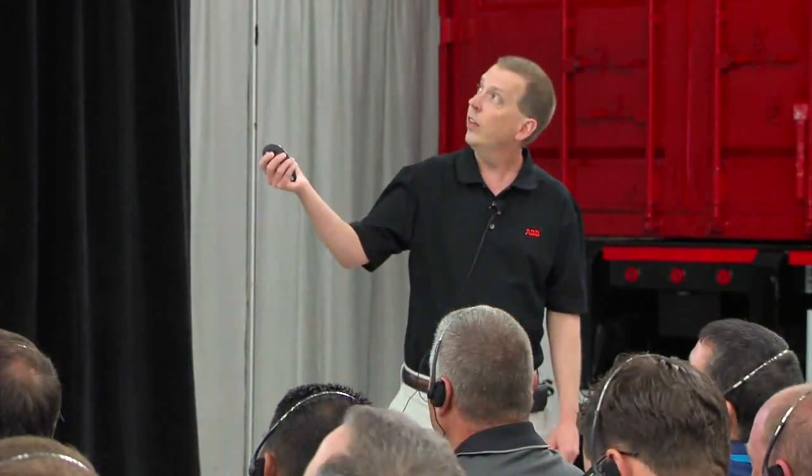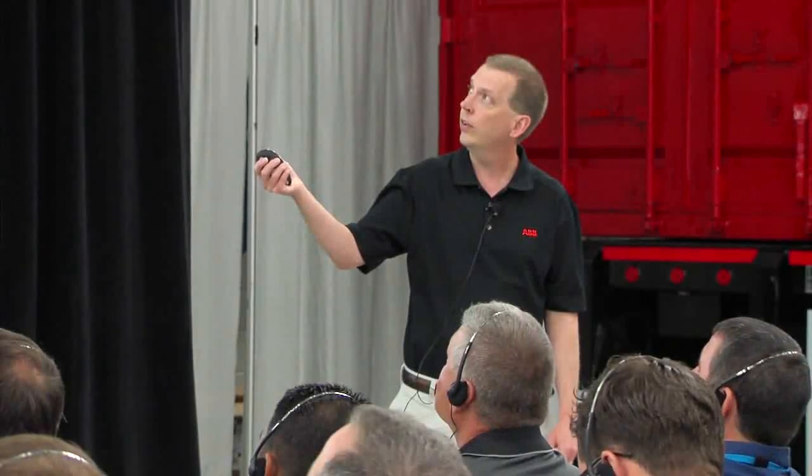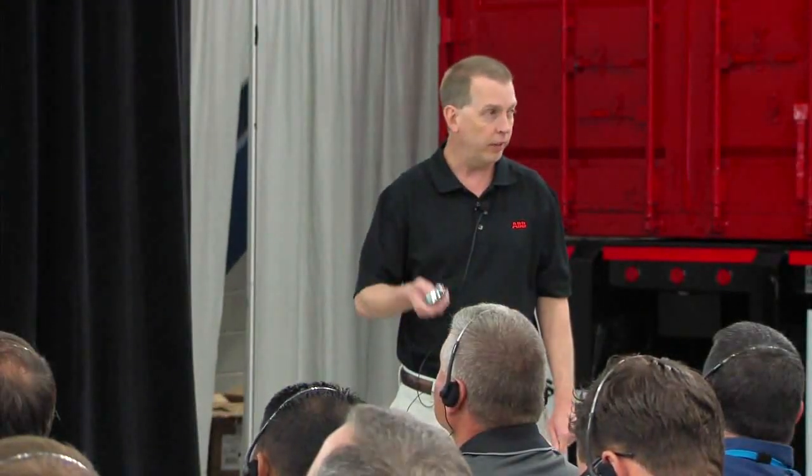In addition, there's 2 sets of ramps. There's ramp accel 1 and accel 2 and decel 1 and decel 2. You can select which ramp you're going to use based on what you want to do. Sometimes you might need a faster ramp and sometimes a slower ramp. You can control that with these 2 ramp rates, and you can have a digital input that controls when one is active or when the other one is active. Maybe sometimes you've got a lightly loaded system and you want to go real quick, and other times it's heavily loaded and you want to go real slow, for example.